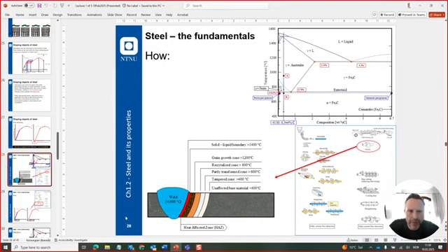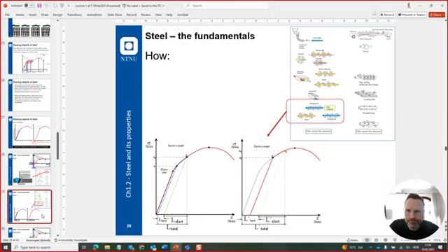We can shape the pipe into any yield that we want in our process of manufacturing. Any yield point that we want, having ways of manipulating the yield point: the percentage of carbon, percentage of micro additives, manganese, nickel, chromium, whatever we do, and work hardening and heat treatment. Balancing everything out together, we get different yield points and different material qualities.